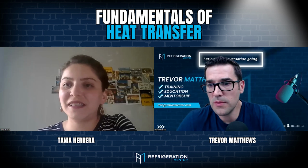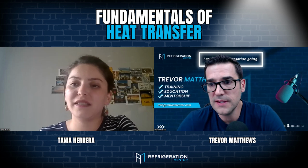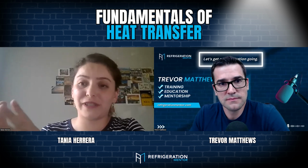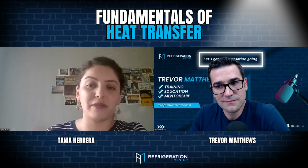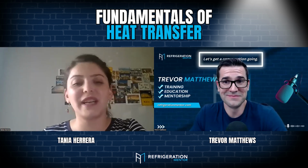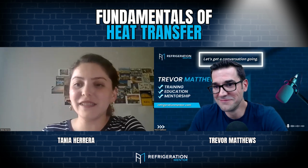The question about the formula is Q equal to U times A times LMTD. Yes, that's the general one. But of course, if you want to calculate the overall heat transfer coefficient, there is another formula for that. And if you want to calculate the LMTD, if it's parallel flow, it's another formula. And if it's counterflow, it's another equation. But I just try to make it simple because sometimes when we see a lot of numbers, it's more complicated to follow in my personal experience. Yeah, no, that's exactly right. I like it simple.